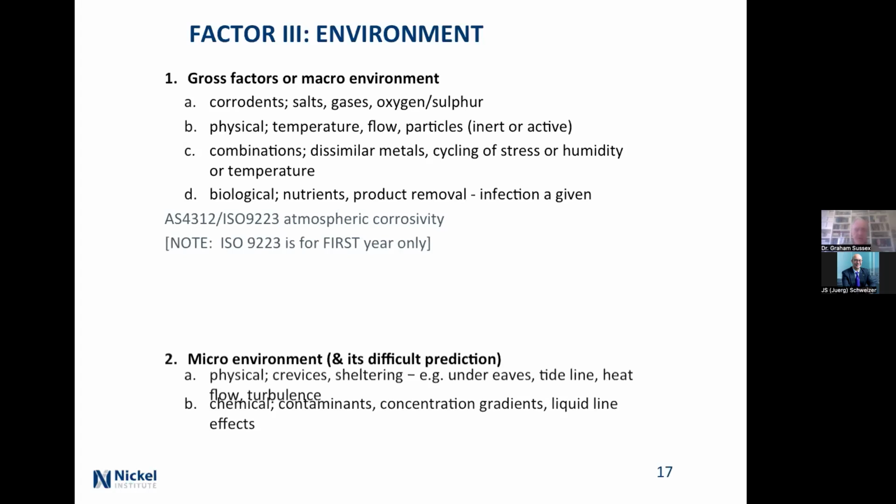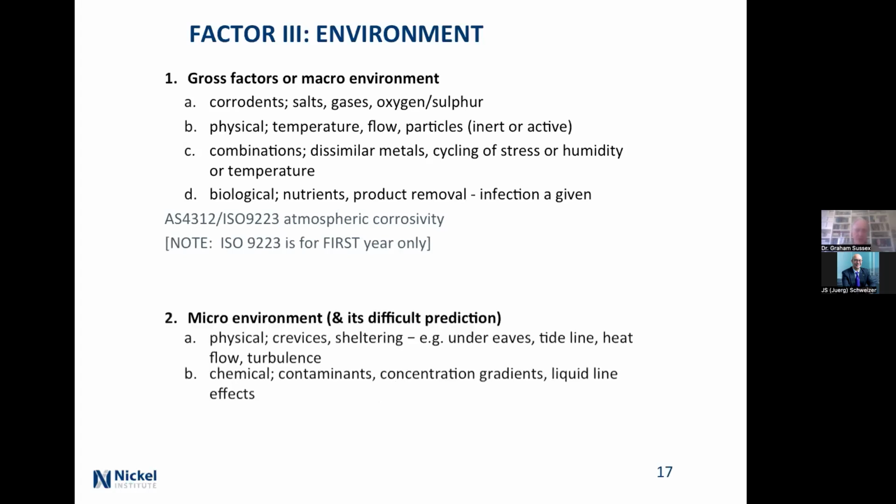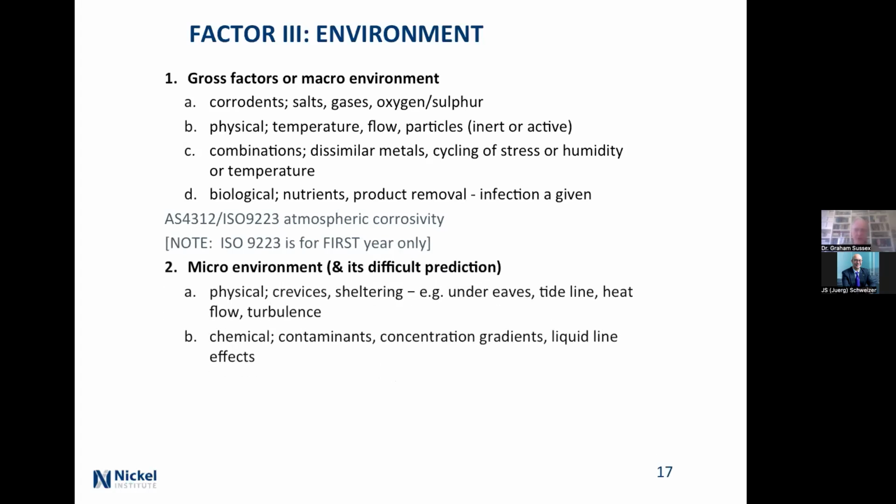Then you talk about microenvironments. Okay, so you've got crevices. You've got things that are bolted together and don't fit terribly well. Talk about sheltering under eaves, sheltering, a tide line. It's not quite sheltering. It's basically the tide comes up to a point, stays there and goes down, or in a tank, you have it at a particular level, and so you can get deposits forming around the water level. And that can be quite a significant corrosion issue.